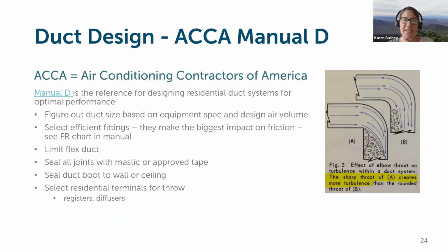As far as duct sizing goes, that's not something that we often see done per Manual D for ventilation. Definitely for heating and cooling, we recommend it. But I'm just putting this out there that the official way to size ducts, even for ventilation systems, would be to use Manual D. And it has a lot of great guidance just in general on selecting efficient fittings and duct sizes and equivalent duct sizes, which we'll get into a little bit.